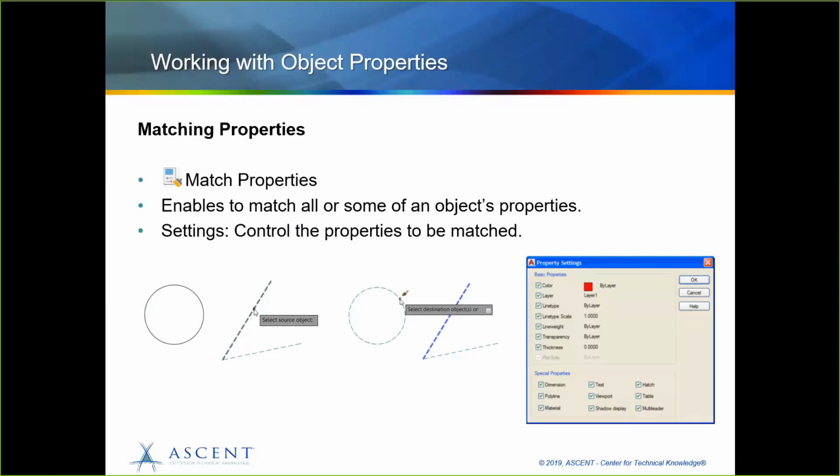When you hover over an object in the second drawing, the object highlights, but it does not display a preview of the new properties. In that case, with two drawings, it does not give you a preview like it does if both the objects are in the same drawing.